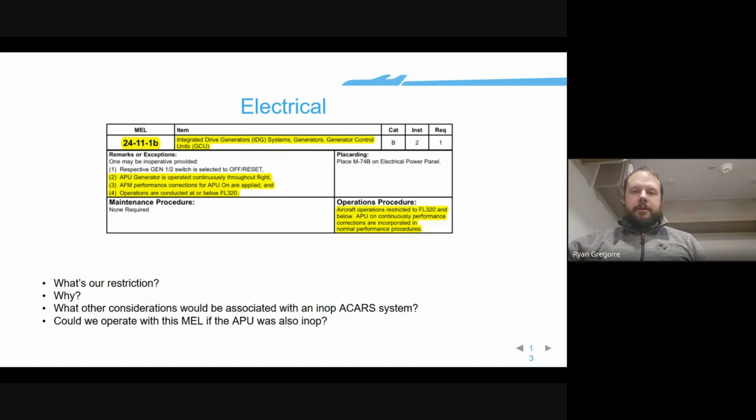So you'll find the nearest suitable airport that meets those criteria, and hopefully ACARS is working, because then you can just ACARS the pilot, recommend diversion to airport ABC. Here's the weather. Here are any relevant NOTAMs. Here's your fuel burn to that airport.